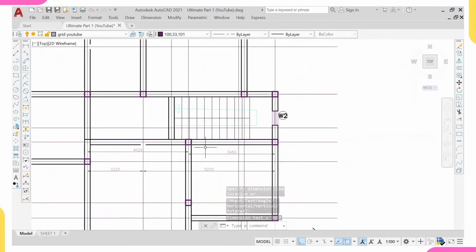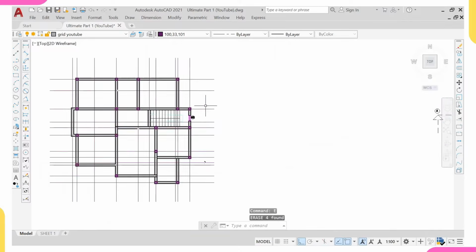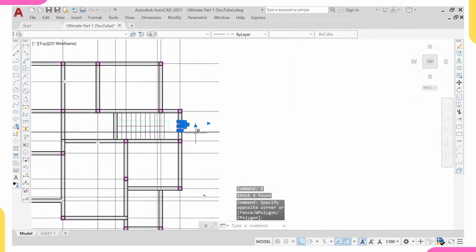And two, this one is not really carrying a point load, it is just carrying a small point load, but there is a beam carrying, let me say, a small load of a slab, a small slab. So for me, this is okay, instead of having a column placed here. So these are part of the things you as a structural engineer need to take into consideration while doing your structural framing. So right now we are through with everything concerning our structural framing.